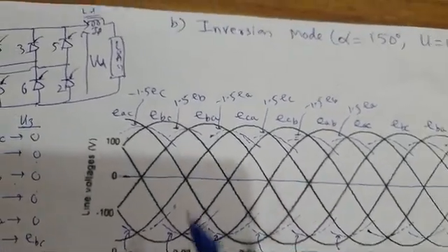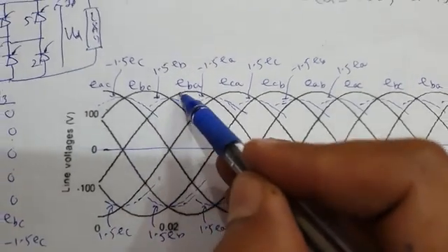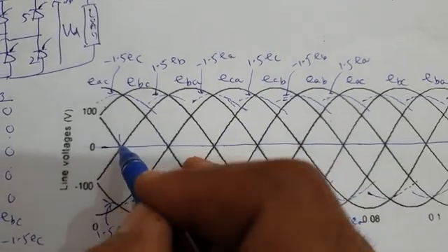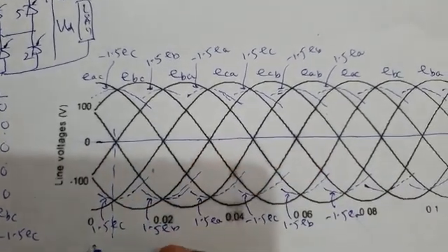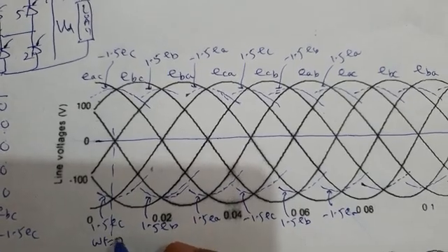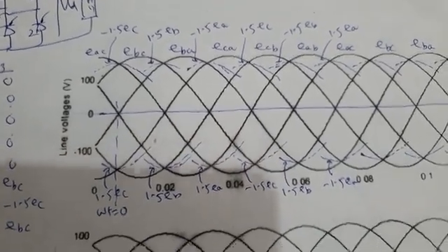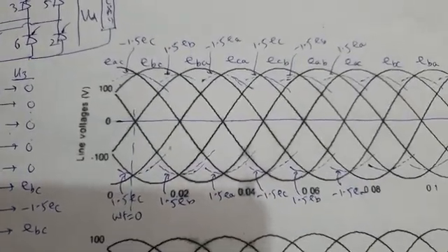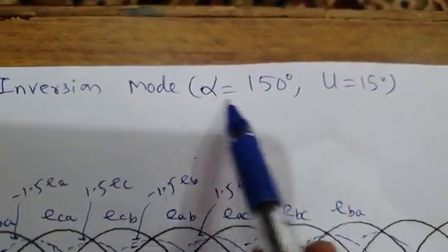Now I have, this is EBA. EBA is this voltage waveform. This is the commutation voltage of valve 3. So obviously its zero crossing is this. So this is omega t equal to 0. So what is my delay angle, or firing angle? My delay angle is 150 degrees.